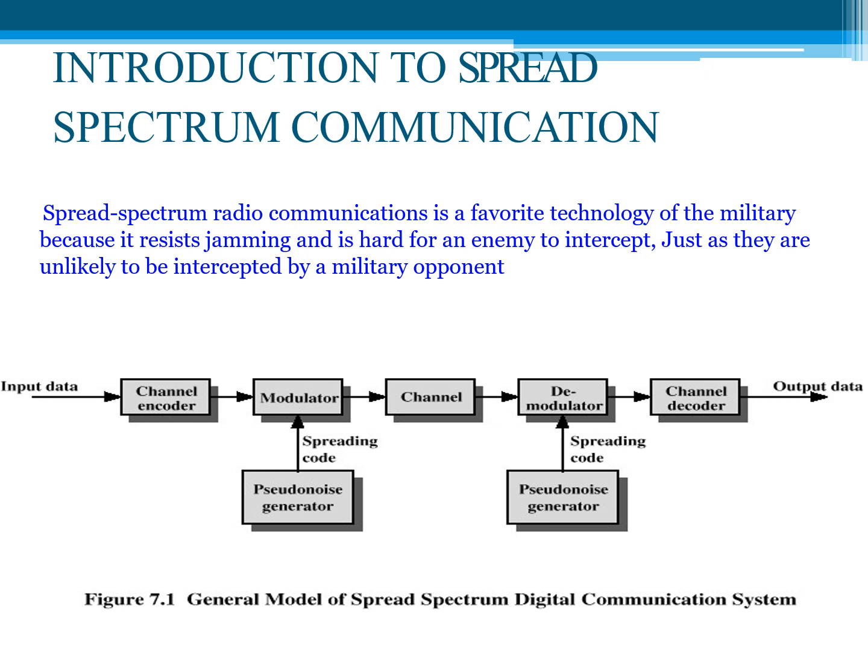This is the general model of a spread spectrum digital communication system. In this we mainly have three parts: transmitter, channel and receiver. First we will explain the transmitter. In the transmitter, the binary information sequence is input to the channel encoder, which encodes the input sequence according to some error control coding techniques. The coded sequence is then given to the modulator. Here the modulator gets a pseudo-random sequence from the pseudo-random pattern generator, which we can see in this block diagram.